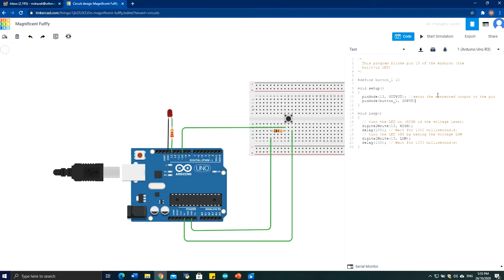If you use the Arduino Mega or whatever, and your Arduino has the internal pull up, you can change this to INPUT_PULLUP, something like that. But in our case, we just use the external resistors as the pull-up resistors to get the input. So the second part is settled. We assign the pin to the input. So now Arduino knows that pin 10 belongs to the input.